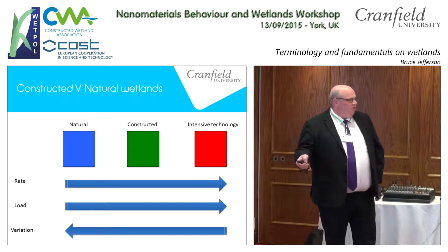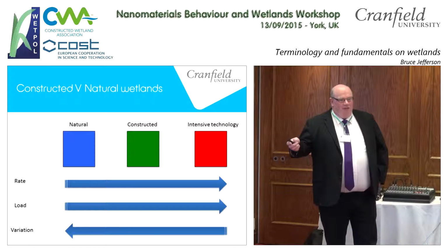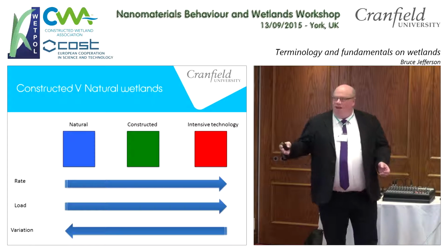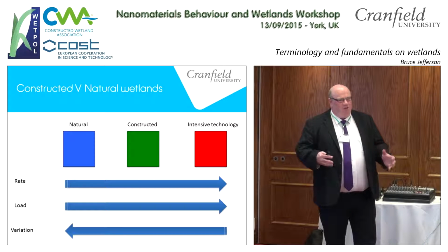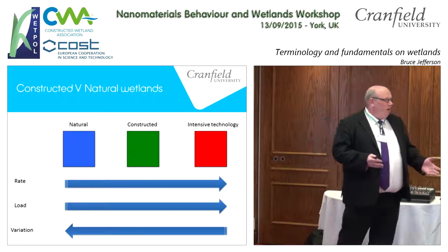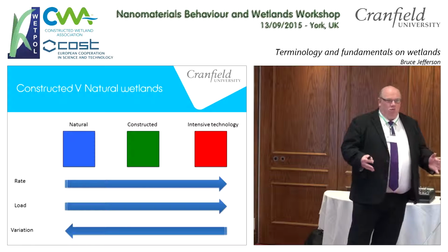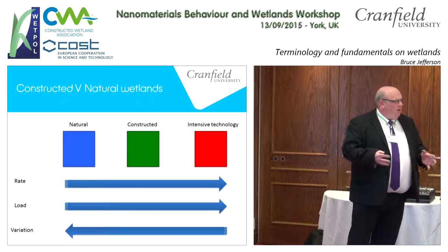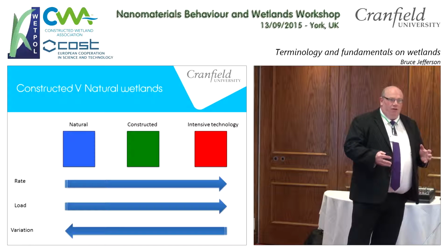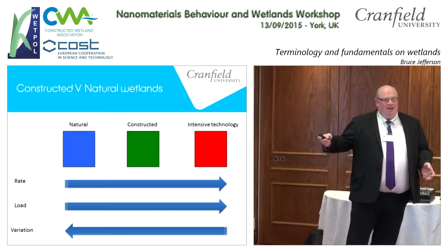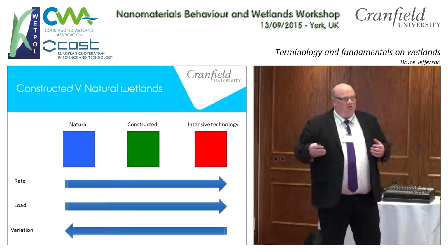In our natural systems they're generally quite low, and they get more intense when I go to the constructed wetland because I'm starting to control it, and then I'm putting most control in my intensive technologies and pushing the water through far quicker. The same would be true of load for two reasons. One, because the hydraulic load is higher, but also in my natural systems I'm tending to experience lower pollution concentrations. So they're dilute and low hydraulic rate, where I'm going to concentrated and high rate as I go up that chain.